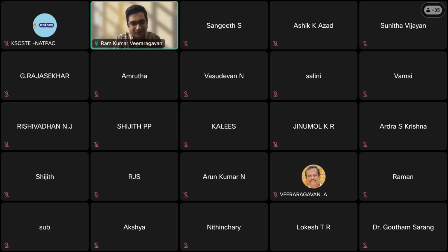So we have to select the appropriate mixes, evaluate their overall performance, and see how they simulate real world conditions. You perform mechanical tests based on some assumption and then see the overall field performance. If they correlate well, then use that number. If not, then you have to tweak the temperature as well as the number of passes being conducted. Does this have any minimum loading pattern?